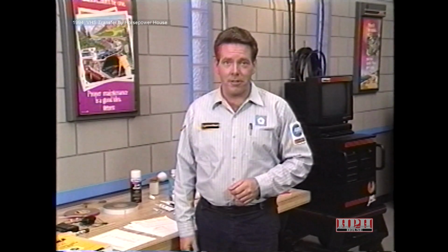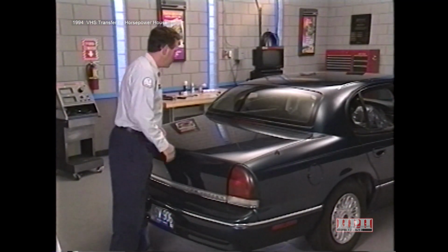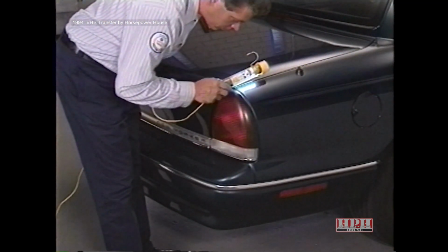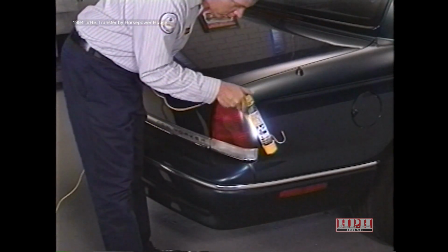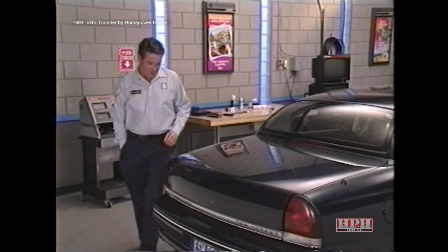Another quick, easy test you might want to try is the light test. This test is used to inspect deck lid seals and welded panel seams and requires the use of an assistant. First, have your assistant climb in the trunk and close the deck lid. Then, using a drop light or a flashlight, illuminate the suspected leak areas, including the area around the tail lights. If the light is visible through a normally sealed location, you have located a possible leak. And don't forget to let your assistant out of the trunk.